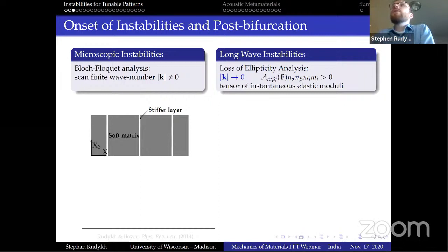The only thing we need to perform that is to obtain the information about the effective behavior of the material in terms of the tensor of elastic moduli. And we just need to satisfy this particular condition for any combination of these vectors n and m, and there are some constraints that will be applied on these vectors, for example for incompressible materials, where n and m need to be orthogonal. But okay, this is a very short two blocks.